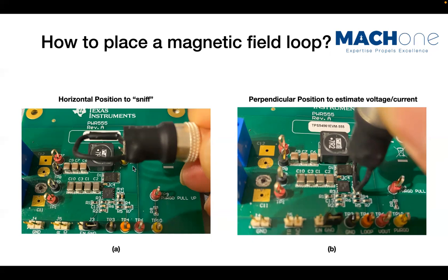With most of the oscilloscopes on the market today, you can select the impedance. You can have 1 megaohm impedance input or 50 ohm impedance input. But if you don't have that function, all you can do is insert a 50 ohm feedthrough through BNC connectors. That will also do the job. So this is an EMC sniffing exercise.